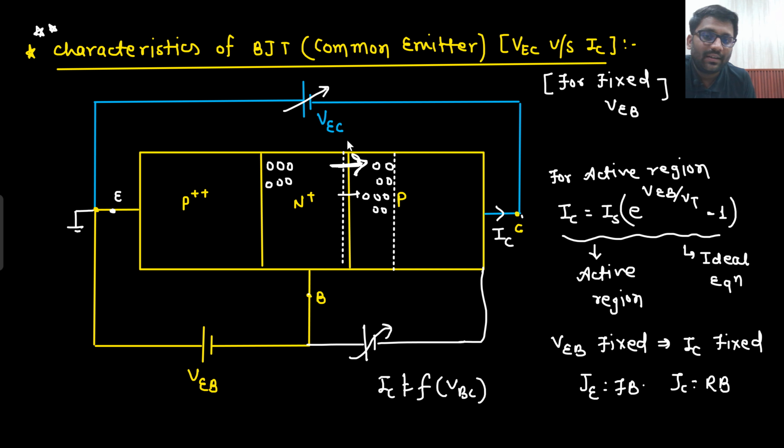So even if you are increasing it, there will be very little effect of this electric field in this particular region. So previously, if it was attracting 4 holes, now also it is attracting 4 holes only. Even if you are increasing this reverse bias, you kept on increasing it, but the effect of that electric field was very little here. These holes first come into action from this electric field, so this electric field will attract these holes. So inside the base, the electric field is not changing much because of the increase here. The electric field is changing much here, not inside the base.